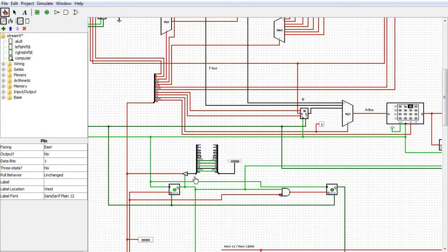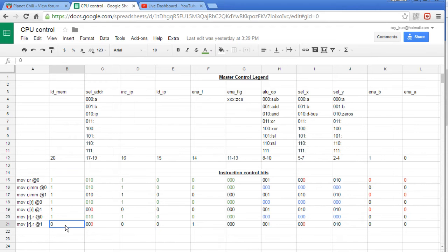So there wasn't ever any error because both drivers were trying to drive it to the same value, and that's fine. The only time you get an error is when 2 outputs are trying to drive the 2 different values. So the problem only occurs because now we're transitioning from a state of driving it to 0 to a state of driving it to 1.